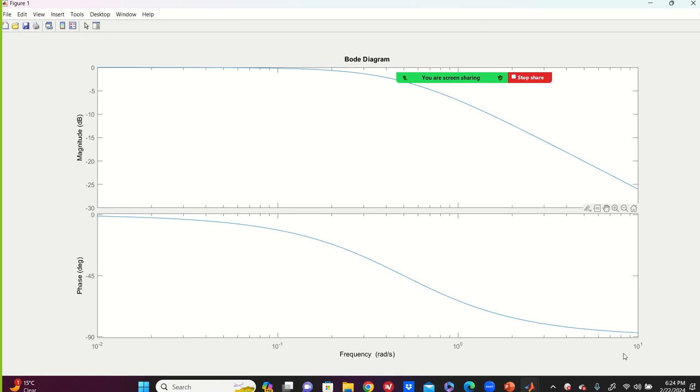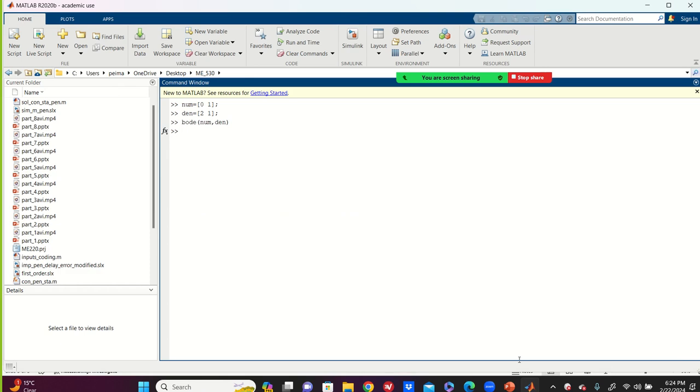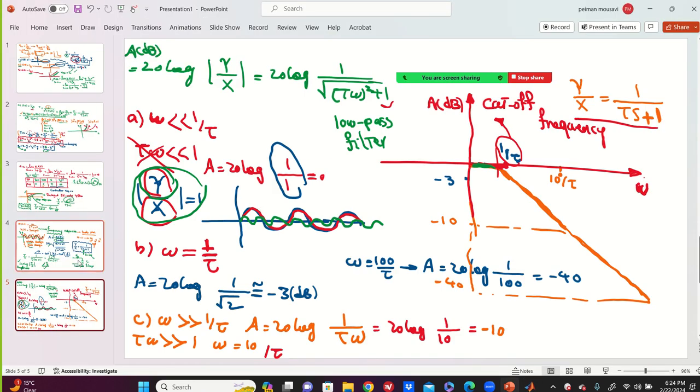I'm gonna do it mathematically now. Okay. So this is the low pass filter Bode diagram. You have a first order system, and this is for that. Now, let me visualize this plot for you guys. See, I said if you have low frequency, output follows input for a first order system. If you have high frequency, as the plot shows, output doesn't follow, you have a decrease.